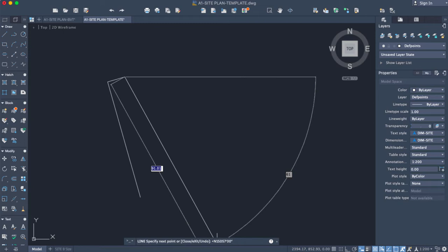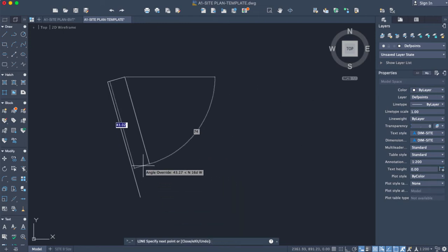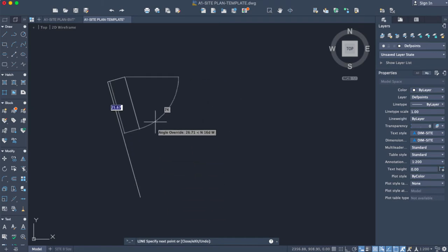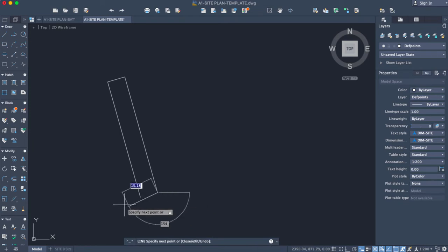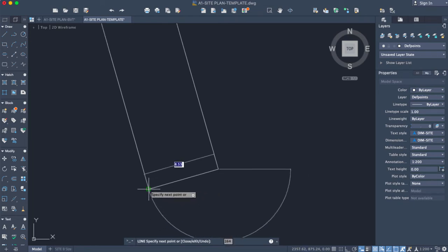And then also the direction, again, it is showing west. Press enter. Once you press enter, move your cursor in that direction. So again, your cursor is basically going in that direction that you enter the survey unit, and then type in the full length. So again, the full length for that line, it's showing 57.18. Enter.